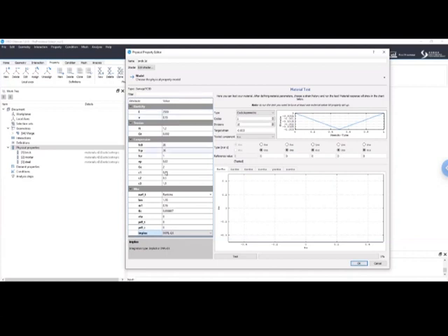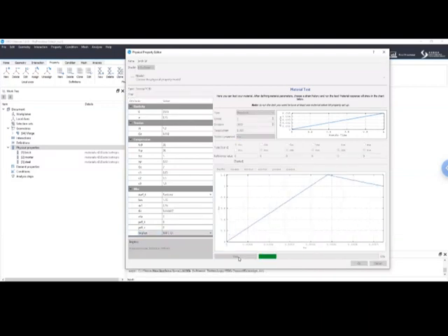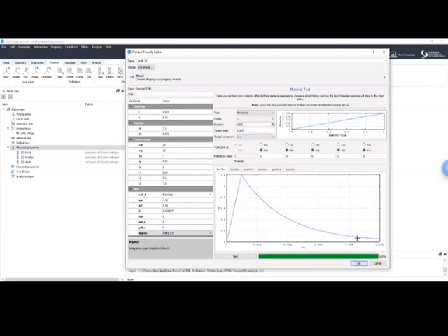Now, let's say we want to see how these parameters are working. We can do it with the material testing. So if you are not sure about how they behave, you can do some tests. Let's start with a monotonic test in tension. So let's choose 1000 subdivisions, and let's push this one up to a tension of 0.05, for example, in the x direction. So let's test it. So this is the behavior in tension. And let's say, okay, this is fine.